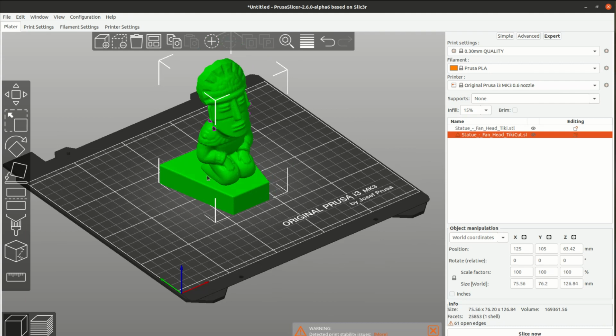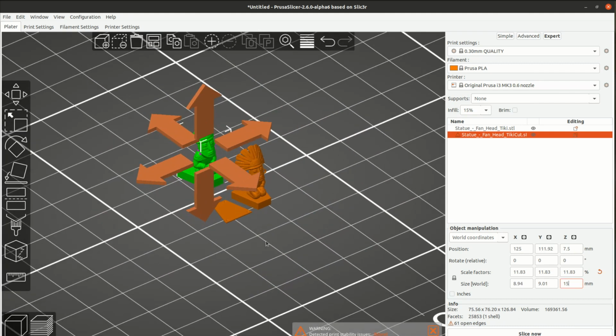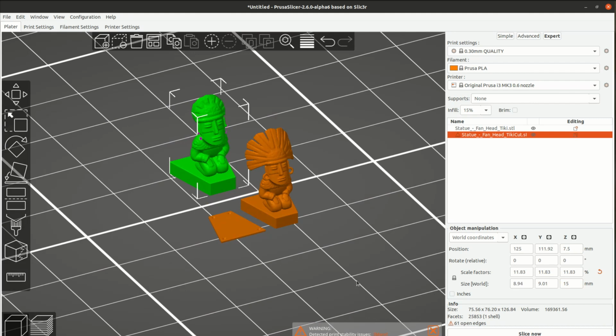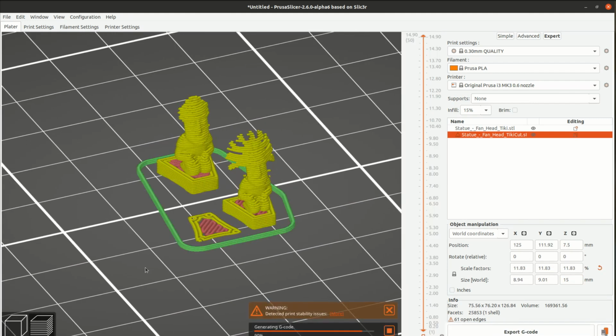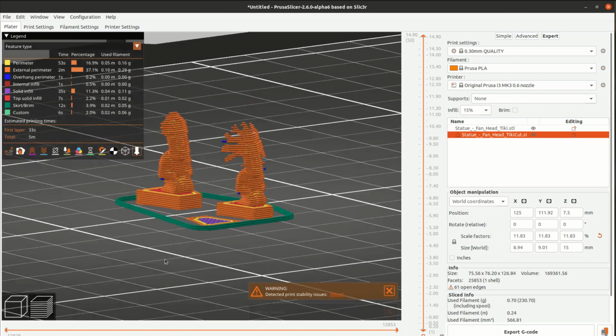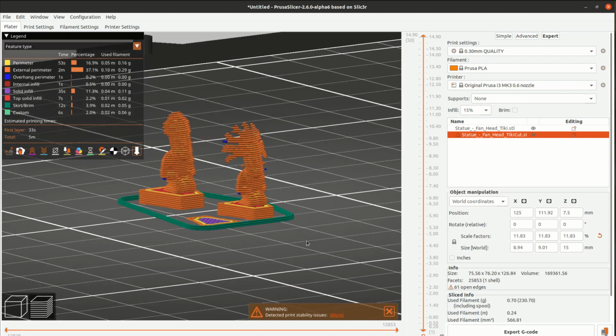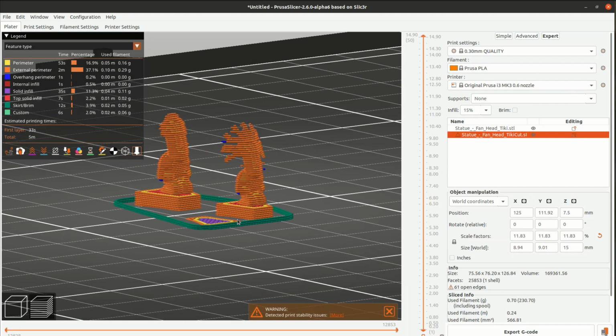It's for sure fine. And when I put it at 15 millimeters high, and you see here, see this model, this is this one. Now we can slice, and you see we don't have the problem of all the hands in the air like this and that. So yes, that is how you can simplify the model from the STL model. Of course, if you have the CAD file, it is easier. But anyway, Blender is strong enough to help you do some simple jobs like this.